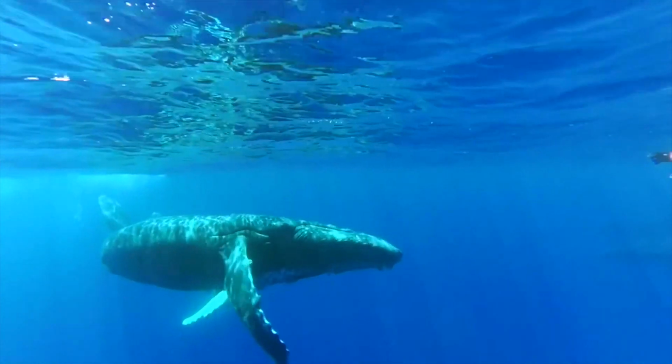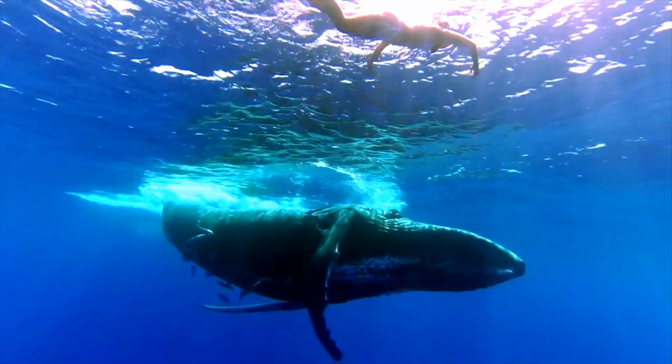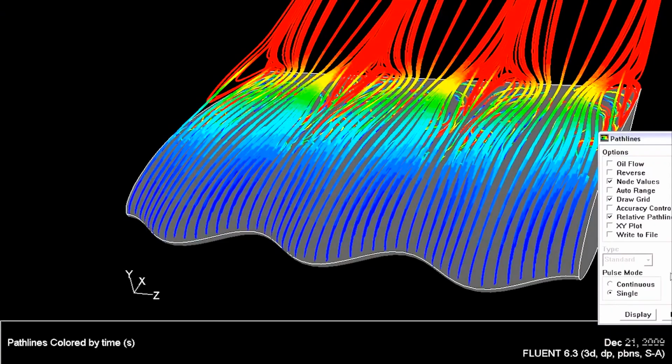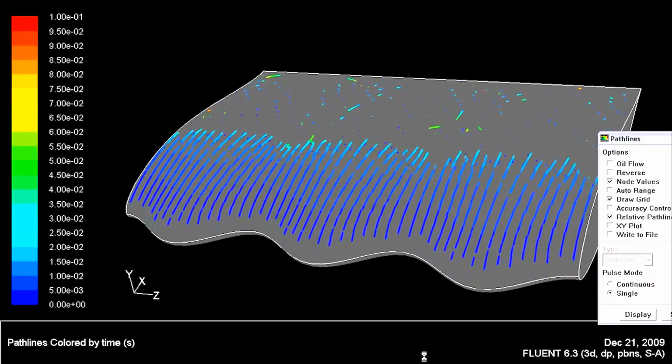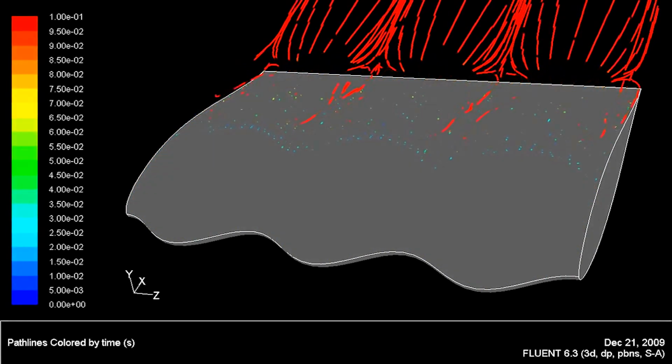Biologists have always admired the swift maneuver of the humpback whale. It has been suggested that these tubercles function as lift enhancement devices, allowing flow to remain attached for a larger range of angle of attack. The tubercle wing design is a fusion between nature and engineering. The main idea of the tubercles is to accelerate flow as they are forced into a channel, which then creates higher velocity over the wing.